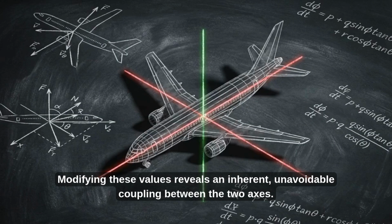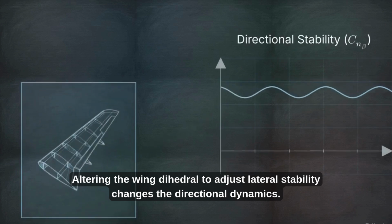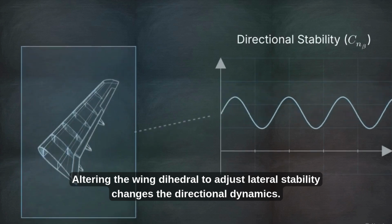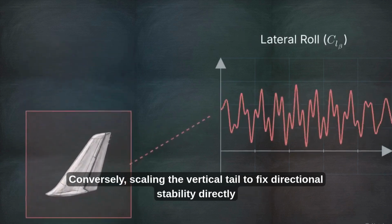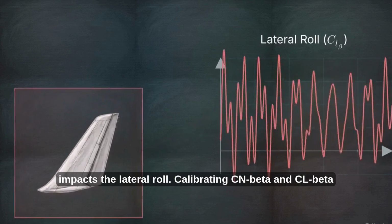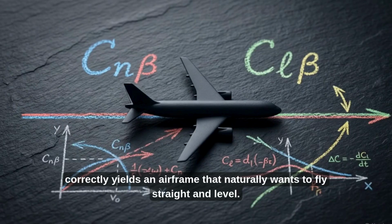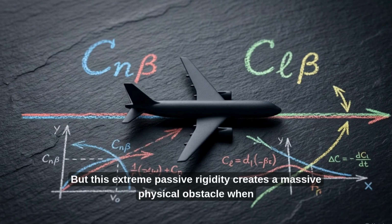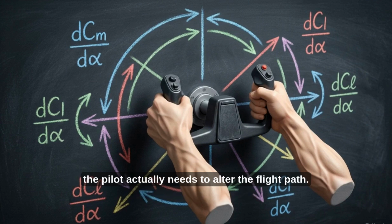Modifying these values reveals an inherent, unavoidable coupling between the two axes. Altering the wing dihedral to adjust lateral stability changes the directional dynamics. Conversely, scaling the vertical tail to fix directional stability directly impacts the lateral roll. Calibrating Cn beta and Cl beta correctly yields an airframe that naturally wants to fly straight and level. But this extreme passive rigidity creates a massive physical obstacle when the pilot actually needs to alter the flight path.